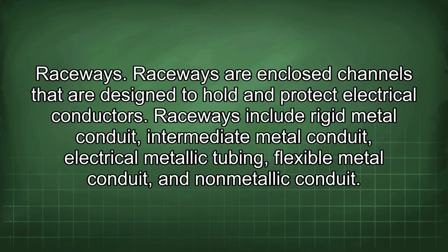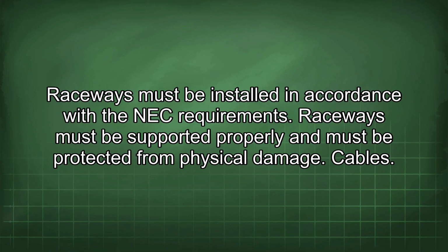Raceways. Raceways are enclosed channels that are designed to hold and protect electrical conductors. Raceways include rigid metal conduit, intermediate metal conduit, electrical metallic tubing, flexible metal conduit, and non-metallic conduit. Raceways must be installed in accordance with the NEC requirements. Raceways must be supported properly and must be protected from physical damage.